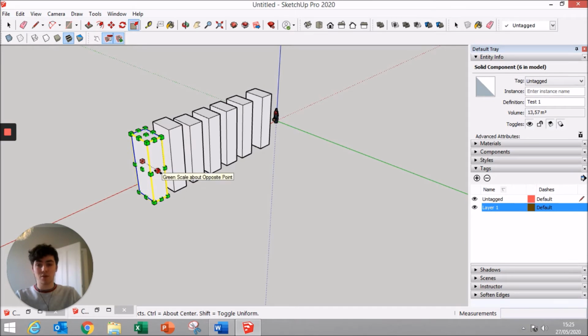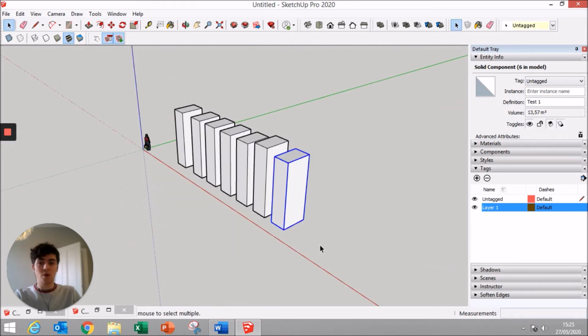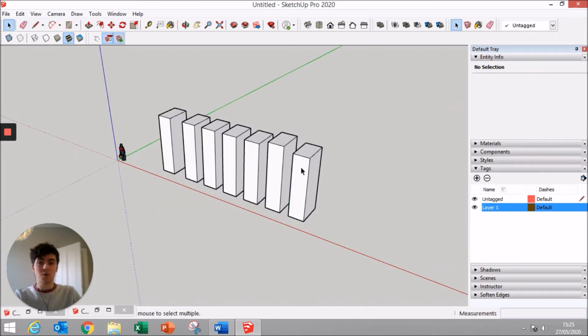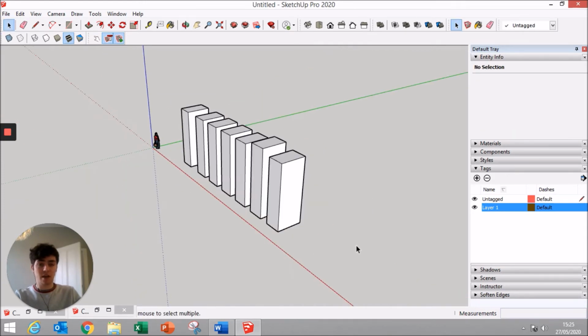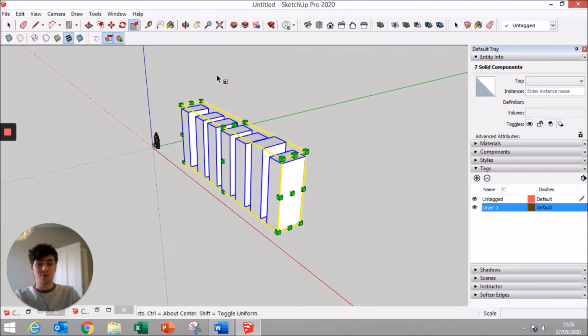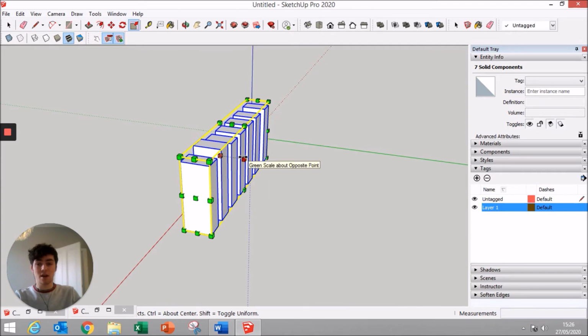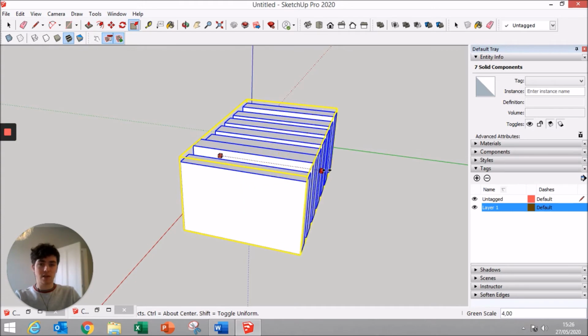And if I want to just scale it a bit, quite useful. If I want to increase the size of each of them, and just thinking that those aren't any more dynamic components, if they're all different, rather than doing them one by one, I can just go select all, go scale tool, and just by left clicking on this green box that goes red now, just going there, and they all change at the same time.